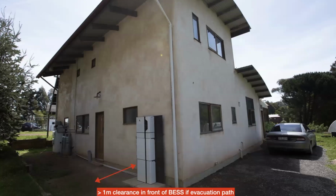Let's look around the back of the house, a wider view here. The rear of the house is quite wide. I need at least 1 meter of clearance in front of that BESS, because that is the exit path from the house, out that door and past the battery system. And so I'm lucky I have got a meter of clearance, but if it was a small block where the fence came quite close to the battery system, I still might not be able to install it there.